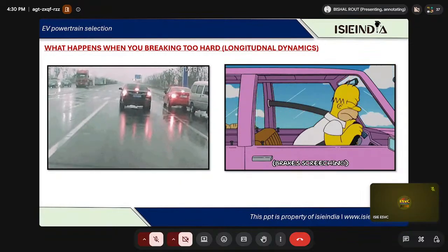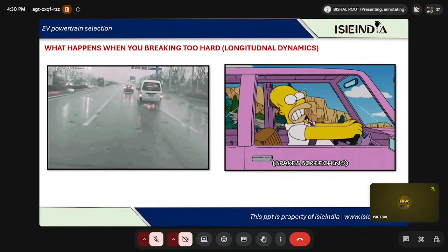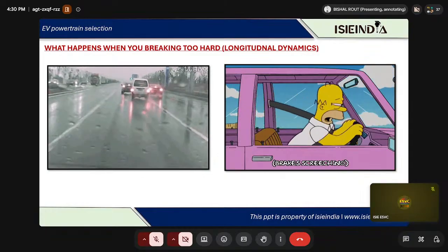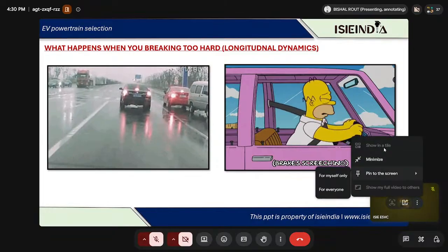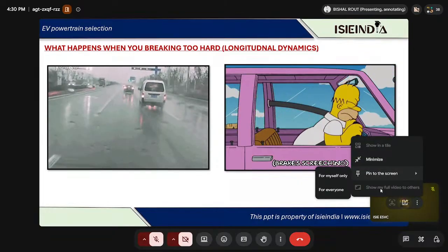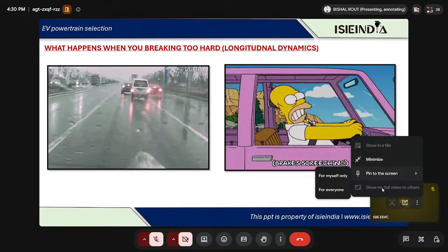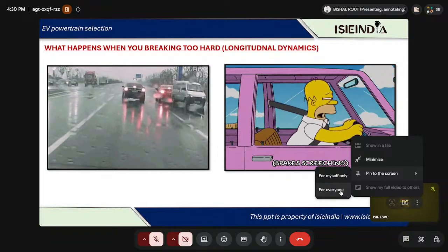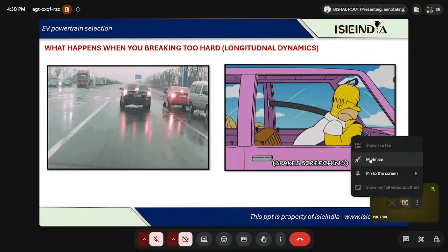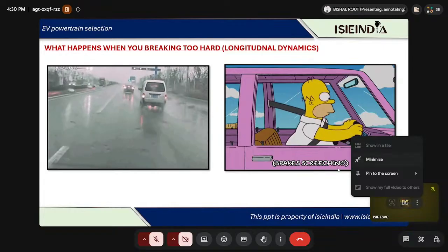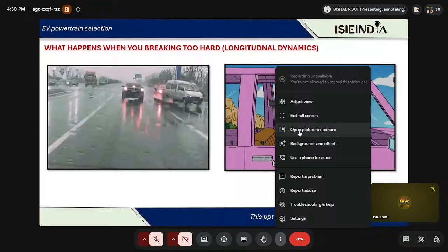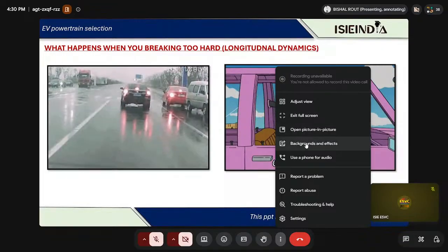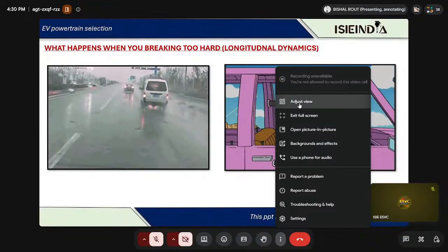Longitudinal vehicle dynamics is the study of motion along a longitudinal axis, whenever your vehicle is traveling in a straight line or in the direction in which the vehicle is traveling. In a normal vehicle, imagine you are drawing a straight line from the rear of the vehicle to the front of the vehicle. That is called the longitudinal axis. Therefore, longitudinal dynamics primarily deals with vehicle accelerations, decelerations, braking, traction, driving force.